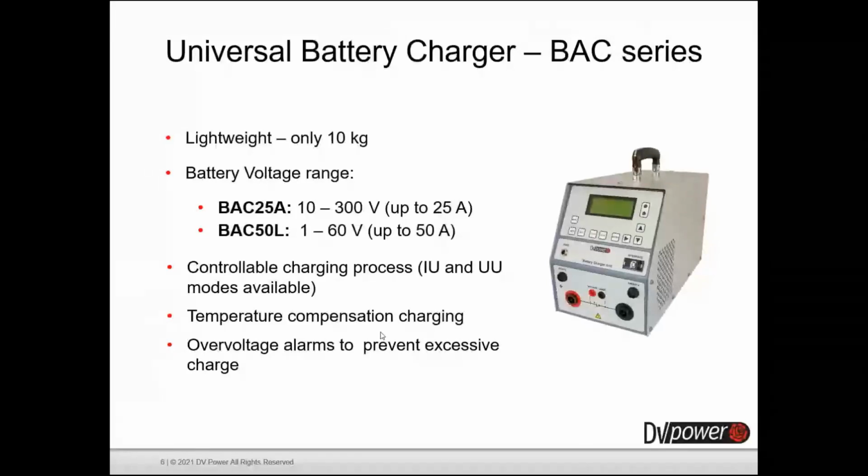We have two modes, IU and UU modes. I spoke about those two modes in this presentation. We have this temperature compensation charging option when you are charging at a temperature that is different from 20 degrees Celsius, as already said, and we have alarms to prevent excessive charge.